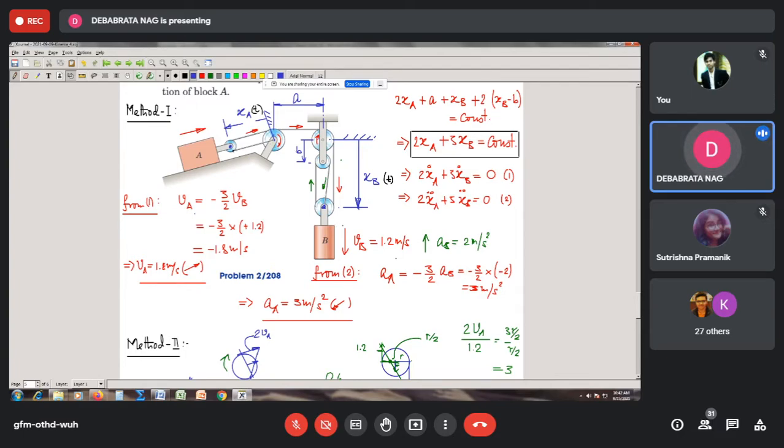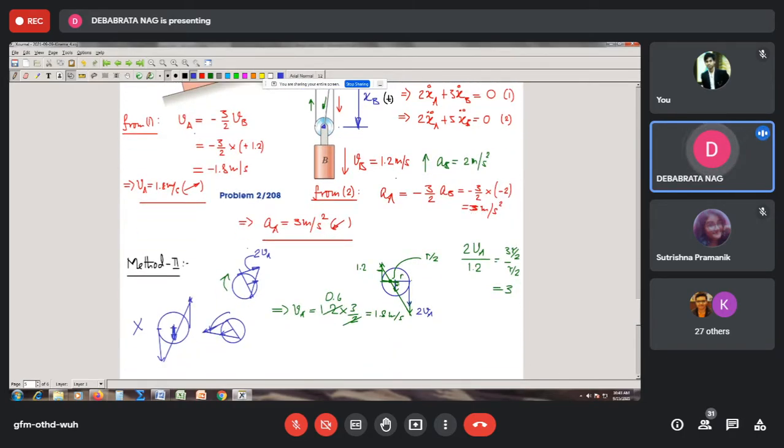So obviously for acceleration, it is obvious that if this one goes up, that means this center is having the upward motion. So essentially it means that all these vectors will get reverted, and ultimately for acceleration, of course, this pulley will be taken to be rotating in the anti-clockwise sense, and therefore by the proper diagram, the velocity diagram over here, we can draw and finish our analysis. So we can therefore say that with these vector diagrams we will be able to solve the acceleration as well.